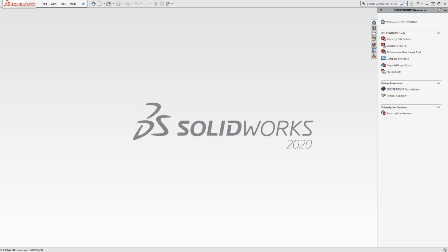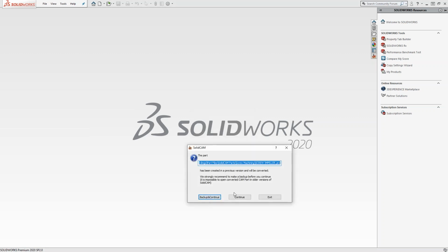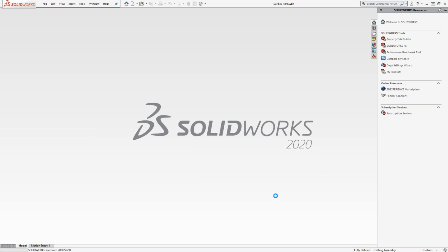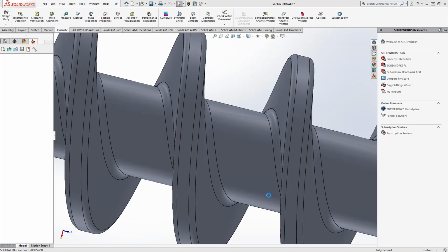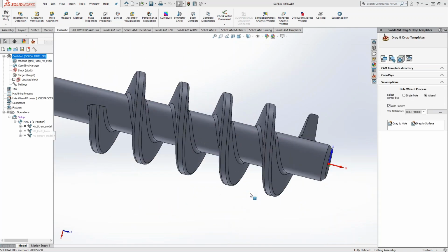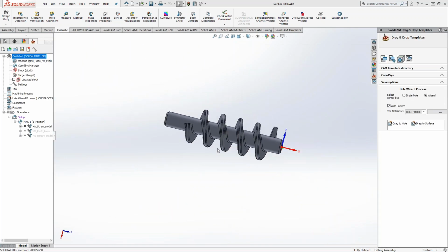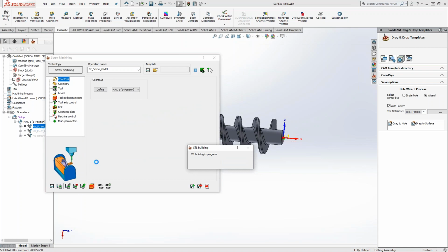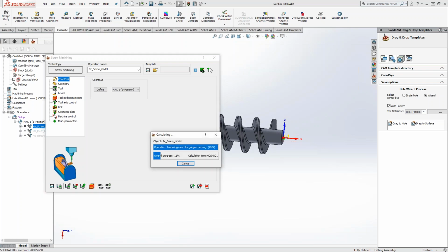go ahead and get yourself familiarized with the HSS first. Yes. And the reason I say that is because HSS and 5-axis are identical except for the tool axis control. So get yourself comfortable with the HSS operation and then go ahead and move to the 5-axis. Now, I'm not saying you can't jump head first into the 5-axis, but it's going to be a little bit easier on you. And I was actually down in Rochester a few weeks ago teaching 5-axis, and our first day was just going over the HSS functionality before we moved over to the 5-axis functionality. So just a little bit of way to get familiarized with it.